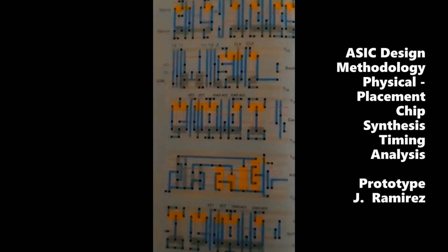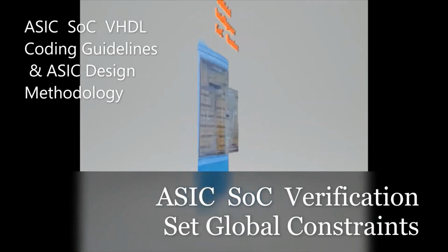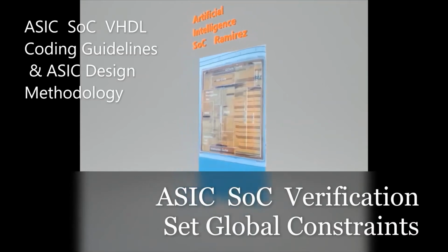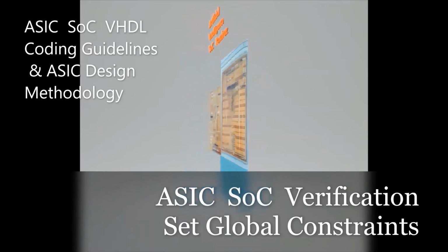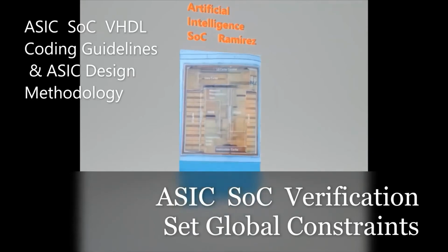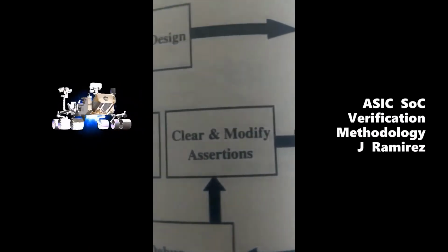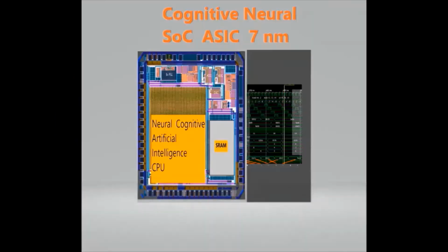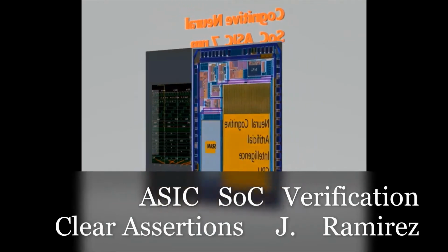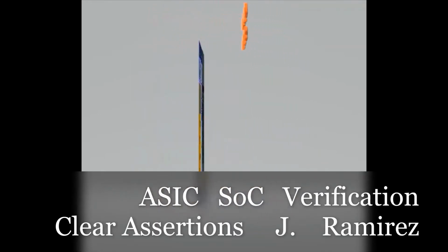Functional verification applied in this project. The primary objective of functional verification is to ensure that this ASIC design meets functional requirements. The functional verification process and methodology consists of gate level event simulation, gate level cycle simulation, gate level hardware acceleration, Boolean equivalency checking, and power estimation.